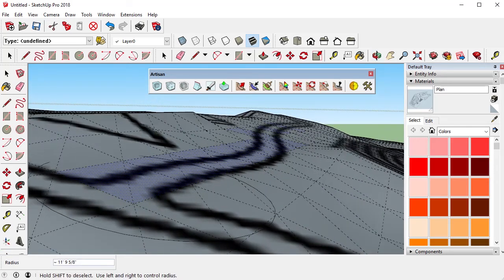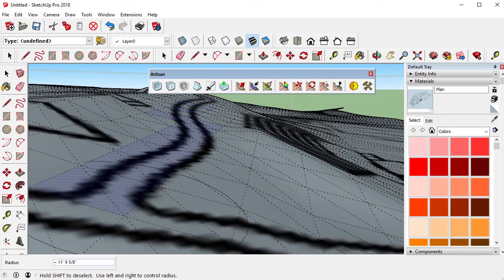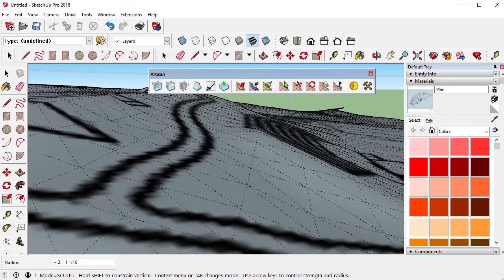What I need to do is sculpt it. If this was one direction all the way straight, once it's selected, I can use the rotate tool and move it. If it was in the direction, I can move my UCS and twist that around. You can twist that surface, but this is not staying flat in my direction. So I'm going to use the sculpt tools here, make the brush really small, and just tweak it. I'm going to pull it down on this side, just draw along this line to make it lower. If you want more detail, you can make it more detail.